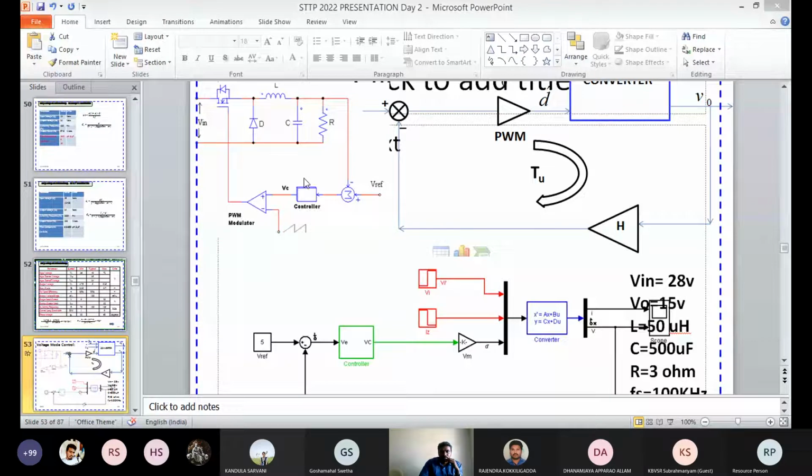So this is the simple buck converter. Here we have some of the components available in MATLAB, so we can directly connect them. But if these components are not available in MATLAB, you must derive the mathematical model with the help of state space averaging or small signal analysis or anything similar, and from that we can develop the MATLAB model.